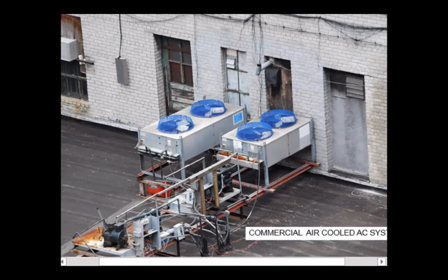And then lastly, like we talked about in logistics, each of these units have a weight, and we have to find a way to pick them to the top of the building. So we need to have a crane that's capable of making the pick, making the reach, and being able to handle that weight. So it could determine whether you have something like a crawler crane that could reach from the street, or some form of a hydraulic crane, or do we need to really have a tower crane or building mounted crane to be able to make these picks? So it all kind of ties hand in hand.